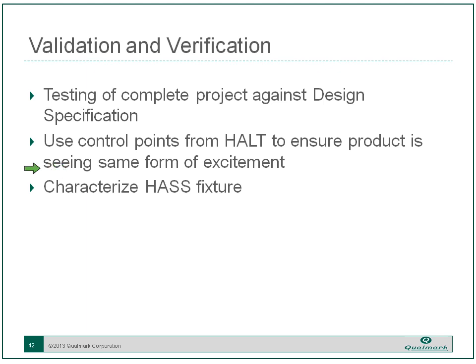We're looking at the spectrums on the vibration and looking for gross deviations, as well as looking at gRMS and looking at ramp rates and looking at how long dwells take to reach thermal equilibrium in that final HASS configuration versus HALT. We get all of this characterized as part of the validation and verification.